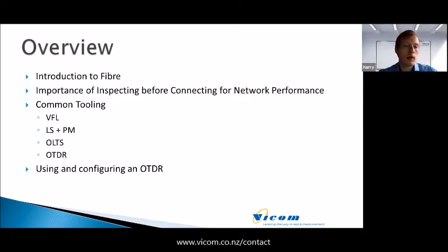They range from visual fault locator, light source and power meter, optic loss test set, and then we're going to delve a bit deeper into OTDRs, not only the operation of an OTDR, how it works, but key things to look at when choosing to purchase one. And then we're going to talk about using and configuring an OTDR to undertake a trace in expert mode.